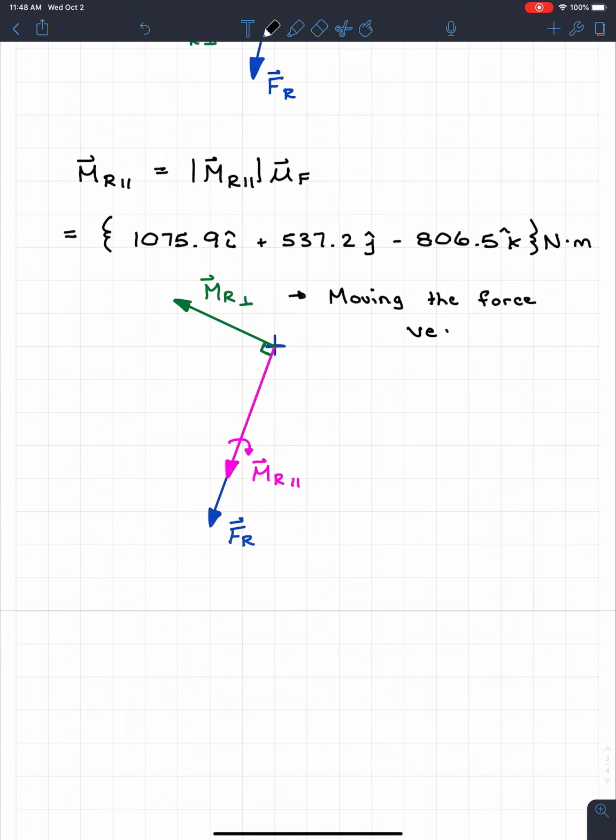All right, to move the force vector, we know how to do it. We've already done it. We use the cross product, and that requires three things. It requires the position vector, but the position vector is actually what we want in the end, so we don't need to worry about it. Actually, we'll write it down. A moment vector is equal to the position vector cross the force vector. This position vector will have the x and the y that we need to solve this question. So that's what we're looking for.